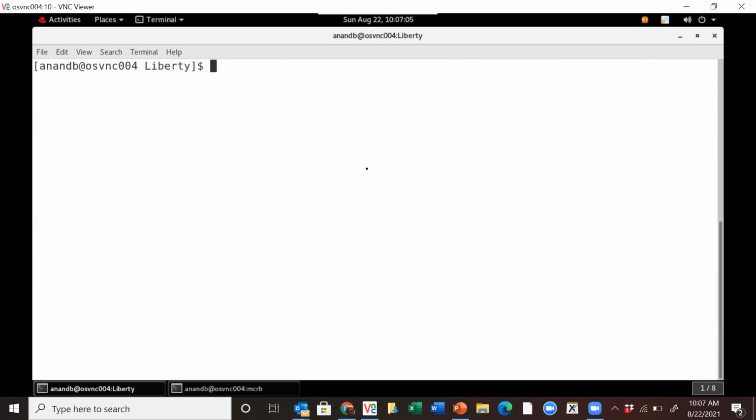So let's explore this library a little bit. I'm going to see how many standard cells there are. So I know, for example, that in the format of .lib, the data for any standard cell starts with the first line being the word cell. Okay, so in this Liberty file, which contains data for all the standard cells in the library, each standard cell's data is organized under a line called cell and the name of the cell.